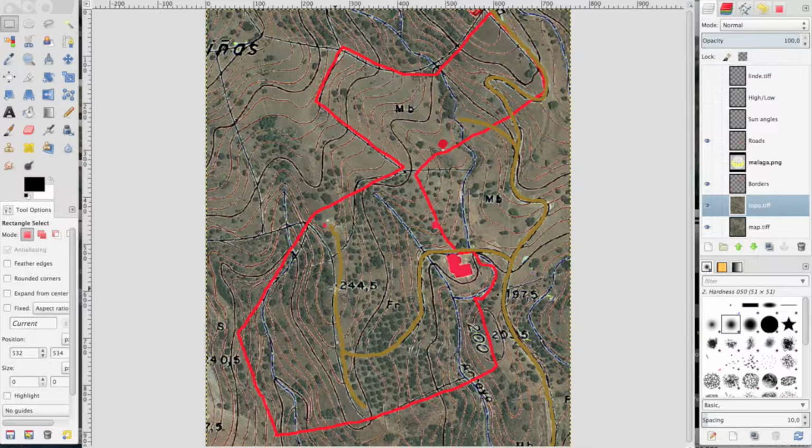Now if we move up, you can see the top of the hill marked out here is 244.5. But you actually can continue up here and see that's the 250 line, that's 255, and that's 260 up here. And you have, but we were pointing in this direction, where again you have the 250, 255, and 260. So you actually have two areas which are the same height, which is the highest point on the property. This we did not see from the ground. So if I'll just color them in green, the high and the low points, we now have those on our site analysis.